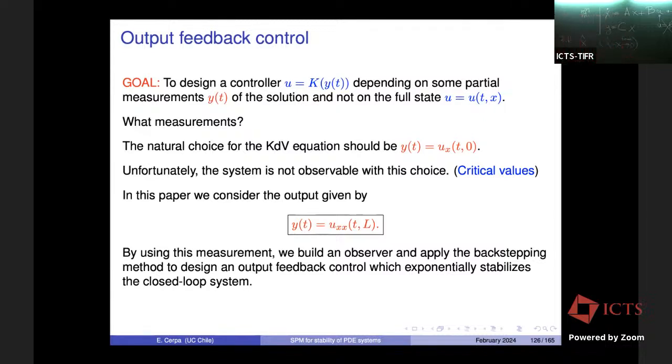There is a very classical method that we're using here, the Luenberger observer, telling you how to get this observer. At the end of the day, instead of putting a control depending on Kx, you consider a control depending on the observer, x hat.